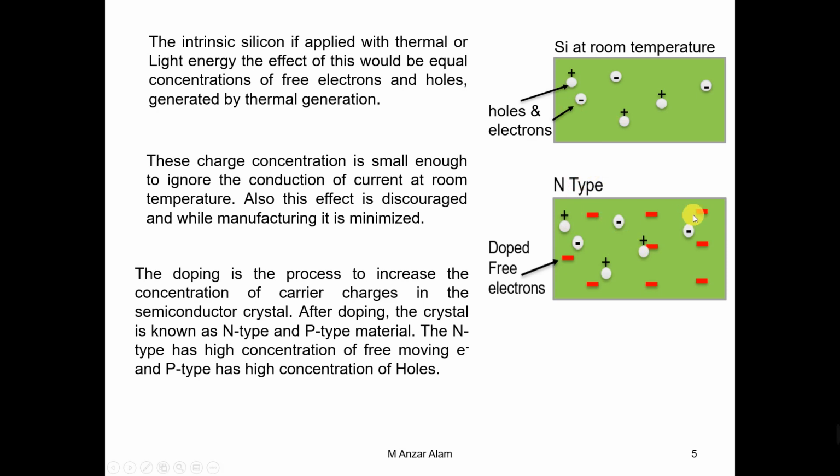So remember, there are different charges, but the important thing is that without the doping material these charges are there, but if we dope with n-type dopant, the free electrons will be this, and these free electrons are really responsible for the flow of the current. It's responsible for the conduction property of the n-type material, and this conduction property is due to these free electrons.